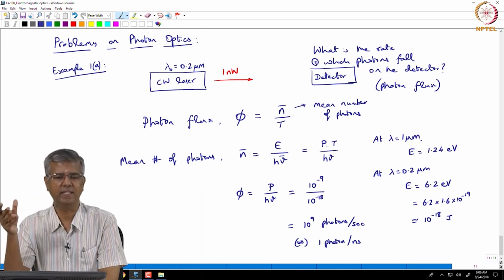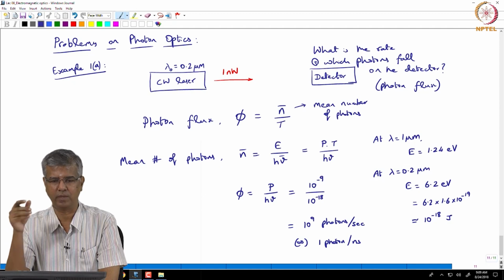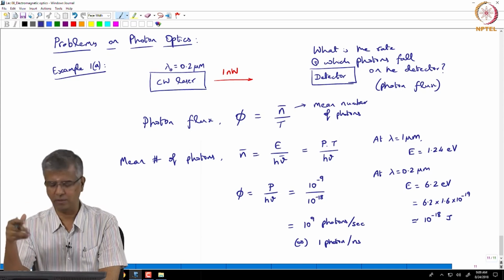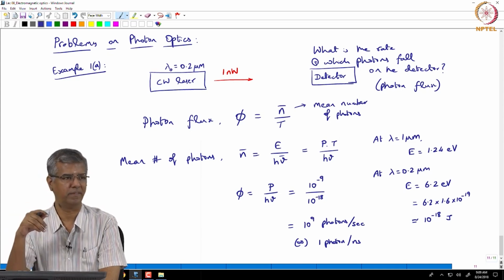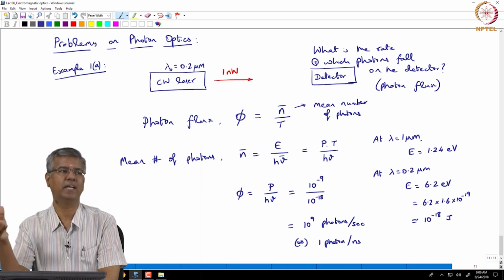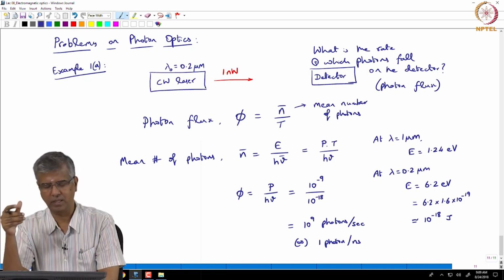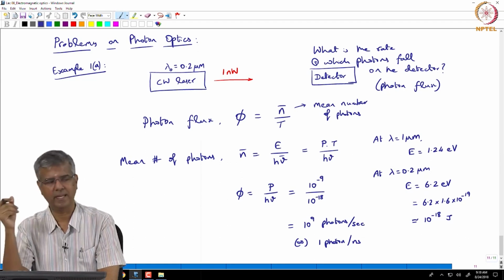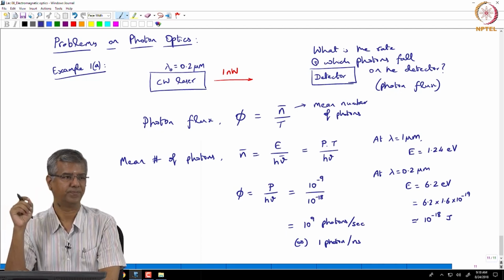So, you take a laser, you know, maybe a milliwatt power level laser, like what you guys have been working with for your demos, right? It's in the order of a few milliwatts. So, you put an attenuator in front of it. You attenuate that to these power levels, 1 nanowatt power levels, and your detector, let's say it's a high speed detector. What I mean by that is it's capable of picking up light radiation at nanosecond time scale.